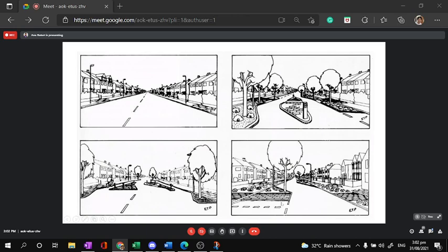The other one is you can do something like this, no? The lane itself is occupied, not by an island but by extending your sidewalk so that the road network in a subdivision becomes narrower. These three will actually help control the speed of vehicles in a subdivision and thereby ensure the safety of the residents in the given area.